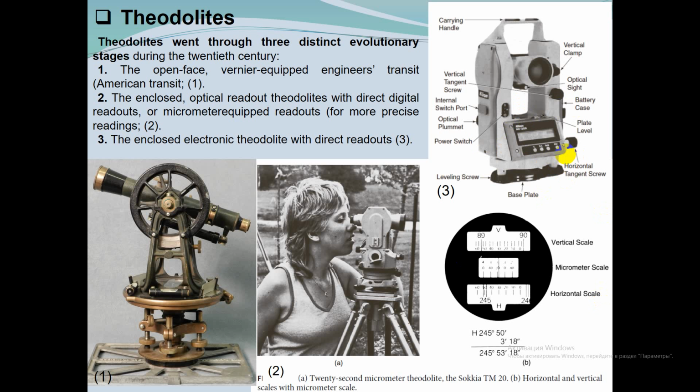So angle reduced can be to 1 second with precision ranging from 0.5 seconds to 20 seconds. This is typical of more recently introduced theodolites. The display windows for horizontal and vertical angles are located at both the front and rear of many instruments for easy access.